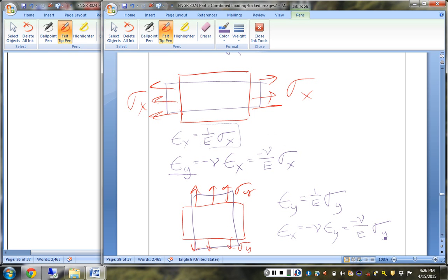Now, we've also got in there, and boy, we only used him like once, the shear strain and shear stress relationship that is the shear version of Hooke's law. What was that one? That the shear stress equals the shear modulus times the shear strain. Oh, yeah, that's vaguely familiar. So there's that shear modulus in there. Now, all of these I have solved in terms of strains, so I'm just going to solve this one in terms of strain so that it's analogous. So I've got everything in terms of strains.